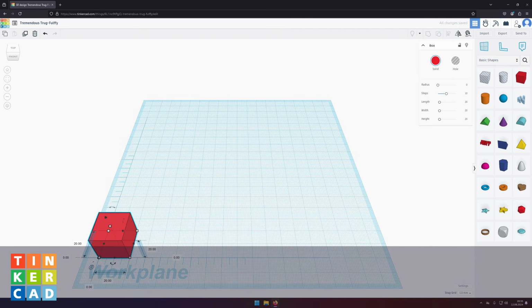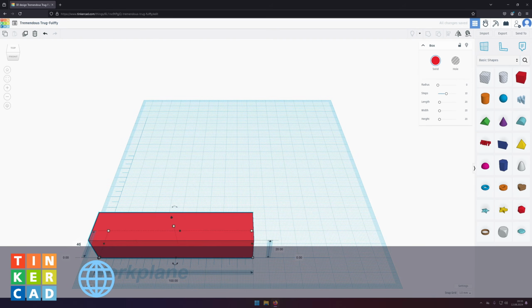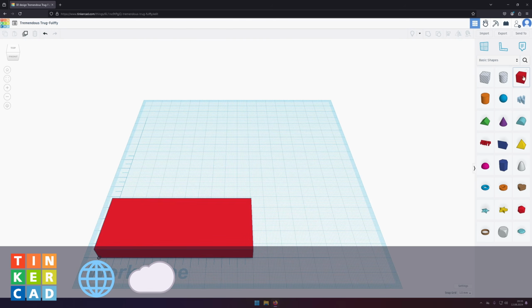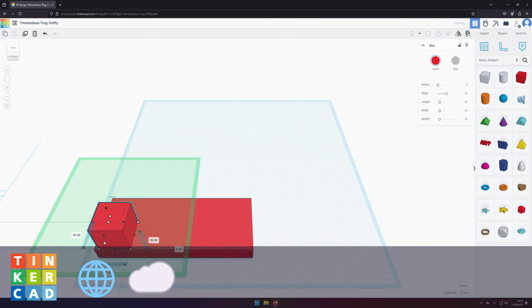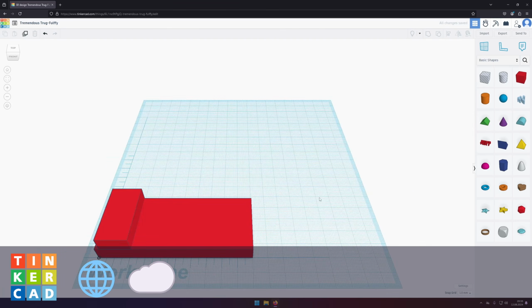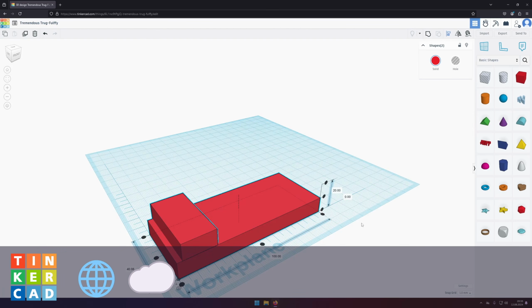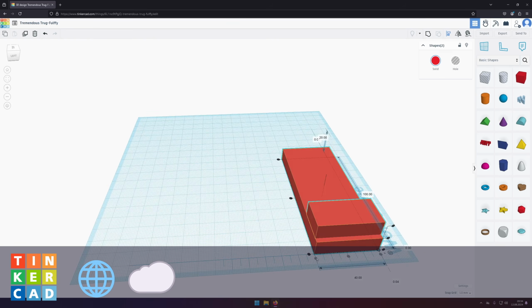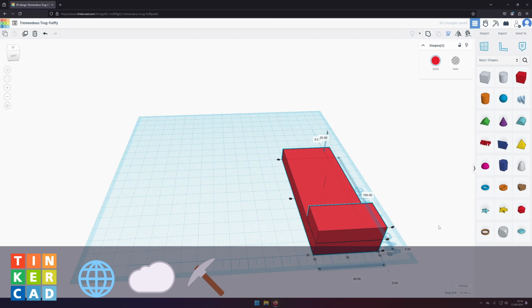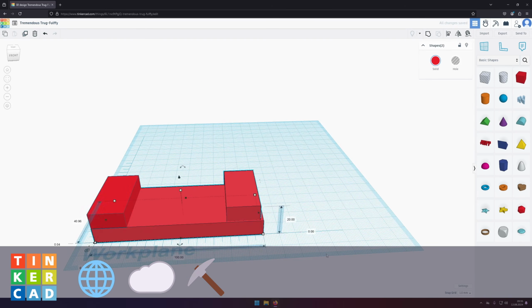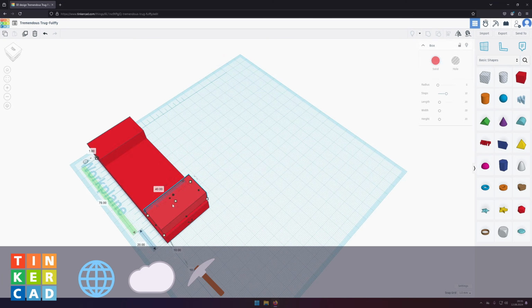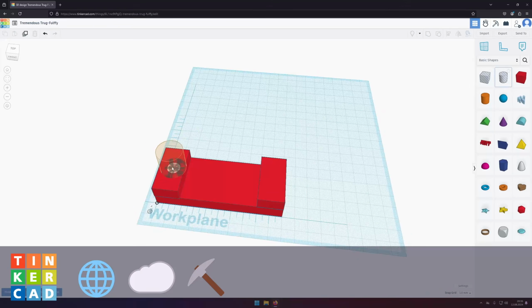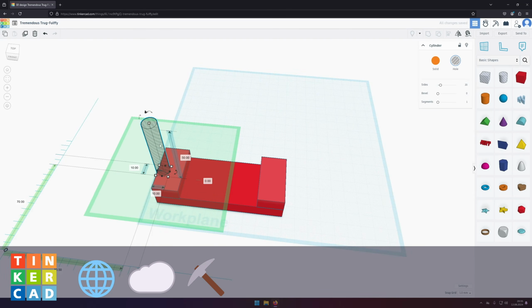Let's start with TinkerCAD. It's a browser-based modeler. That means that your files will be stored in cloud as well. You will be able to export those files for 3D printing, but remember the main storage for your project will be cloud. You'll see that I'm pulling some shapes in the viewport, changing their dimensions, and pushing and pulling the part. So this is how you use TinkerCAD. You have a choice of predefined shapes, or you can use designs from user-created libraries. Then you align those parts, combine those parts, and subtract those parts to get to your final design.